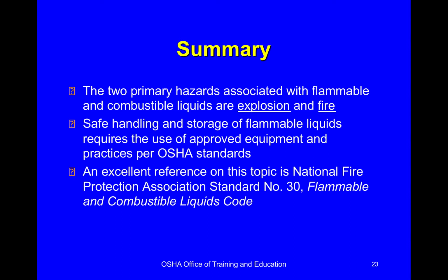So here's a summary of what we've talked about. We have two primary hazards associated with flammable and combustible liquids: explosion and fire. We need to practice safe handling and storage of flammable liquids, and require the use of approved equipment and practices per OSHA standards. A good reference for this is the National Fire Protection Association Standard Number 30, Flammable and Combustible Liquid Code.